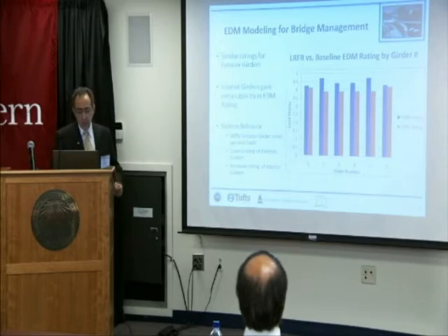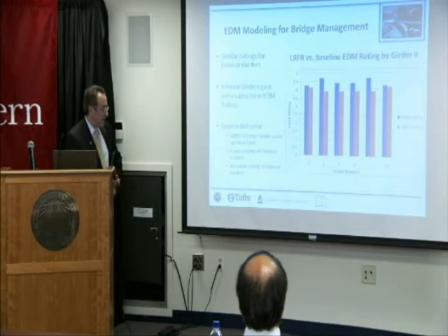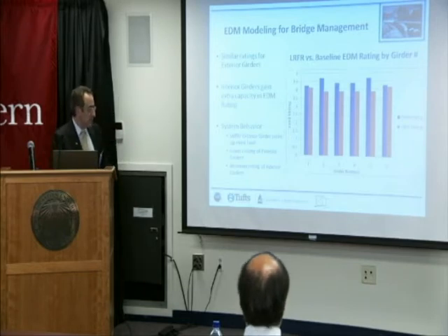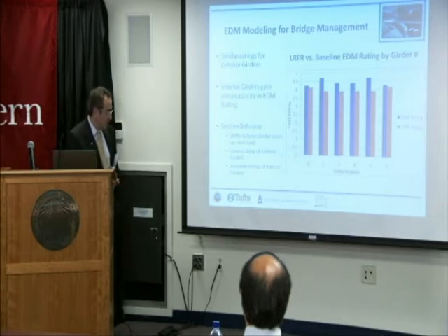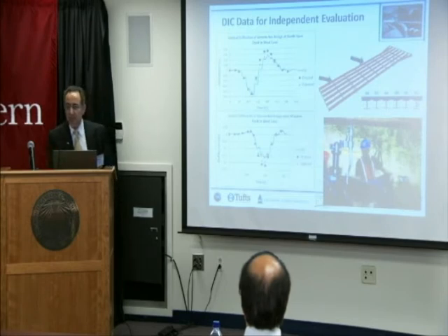And again, we see similar ratings at exterior girders. Interior girders gain extra capacity. And in terms of system behavior, we see stiffer exterior girders that have the concrete portions of the parapets on the top of the concrete deck, and that basically increases them, making them superior in terms of load rating.